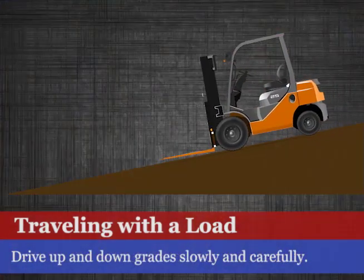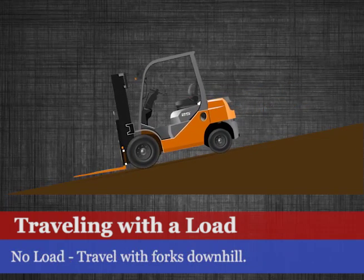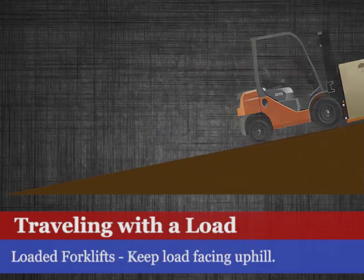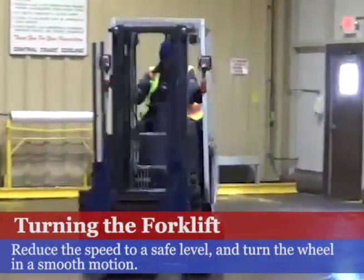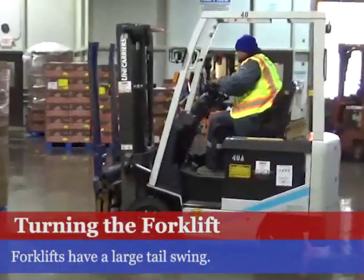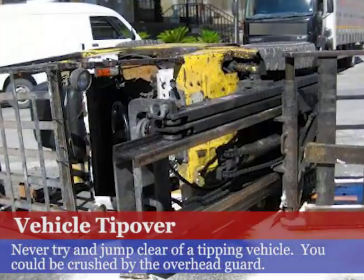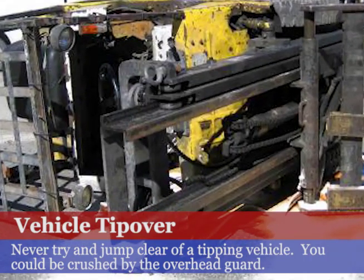Slopes must be ascended or descended slowly and carefully. If you are going up or down a slope without carrying a load, the forks should face downhill. If you are carrying a load, the load should always face uphill. When turning, reduce the vehicle speed to a safe level, and turn the wheel in a smooth motion. Remember that the rear wheel steering will cause an exaggerated tail swing. If the vehicle tips over, hang on to the steering wheel and lean away from the fall. Never try and jump clear of a tipping vehicle, you could be crushed by the overhead guard.